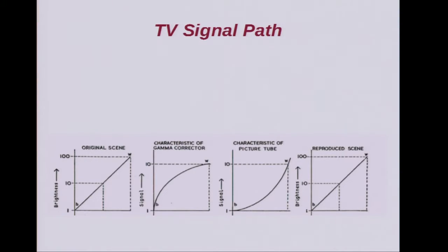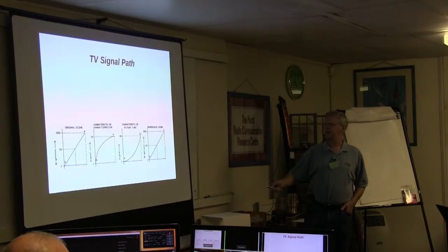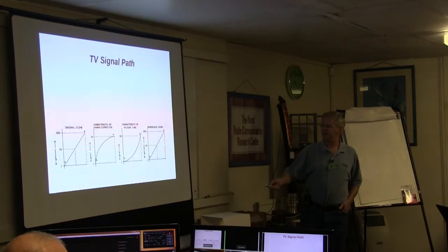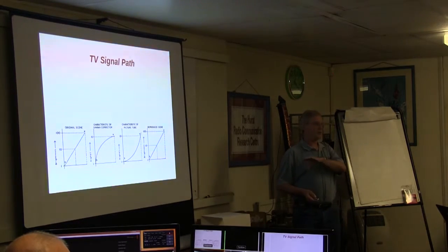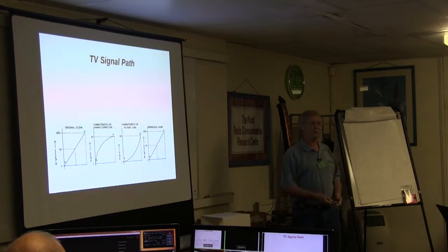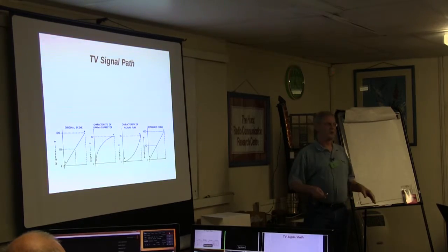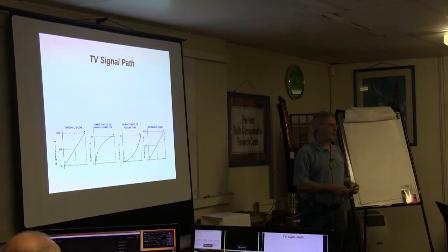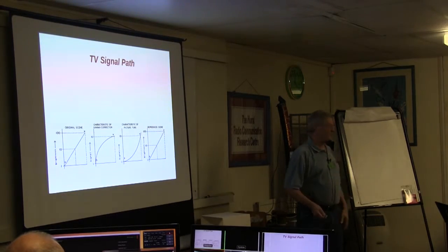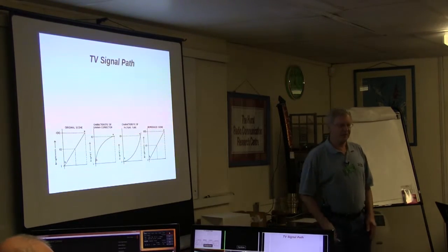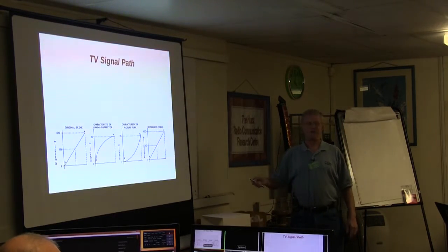But you've got this picture tube in there, so it's going to take a linear signal and modify it. So somewhere in the chain you need something to put that right. So you need what we always knew of as gamma correction back in the camera. So back at the studio, or particularly in the camera usually, was this gamma corrector. All of us who've worked with cameras with linear transducers in them have come across gamma correctors in the past. Those of you who only played with Vidicons may not have found it. The Vidicon happens to have about that kind of characteristic, and it kind of works good enough. So that's the reason for needing gamma correction somewhere along the line.